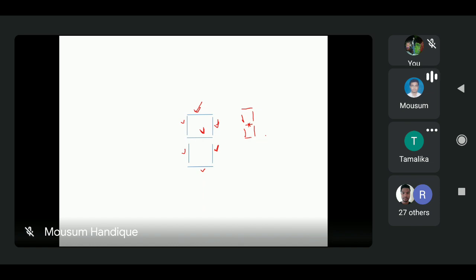This way you can construct the truth table first, showing the behavior. So its name is 7 segment BCD. 7 means when all the segments are active, the total number of segments is 7. And why are we calling it BCD? Because we can represent from 0 to 9. Now, how can we construct this particular problem with the help of a decoder?